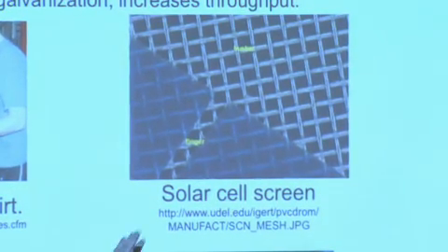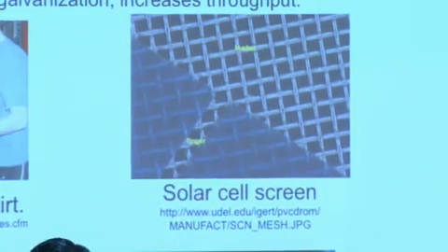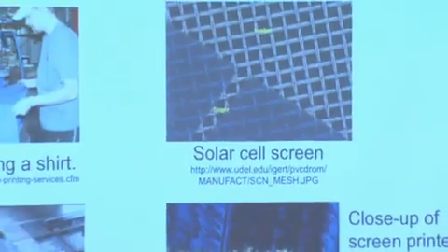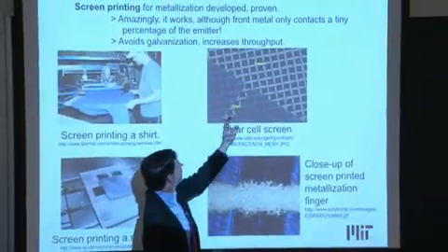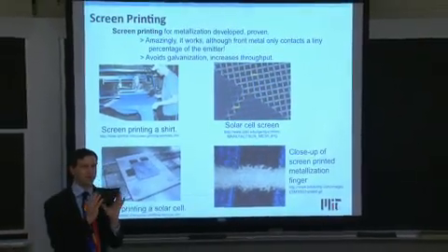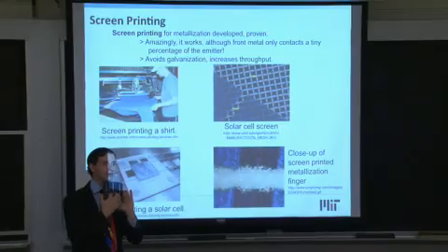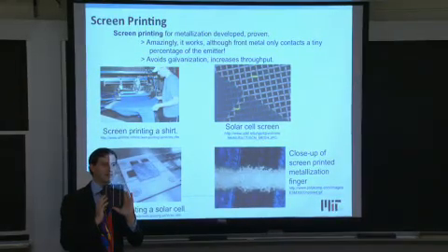And here there's a polymeric coating of the screen, which prevents the metal from going through the screen at those places. So it shades the solar cell underneath and prevents metals from being deposited there. And you have fingers and bus bars: the thin little fingers that you see right here going sideways, and the vertical bus bars that you see going vertically right here.